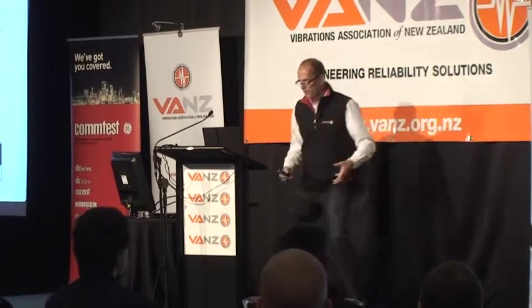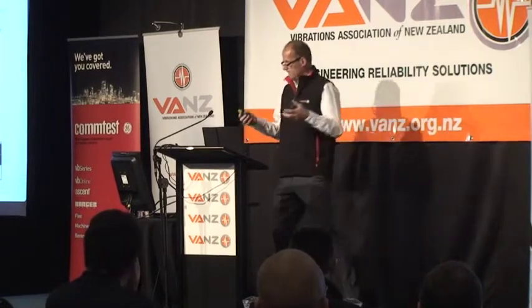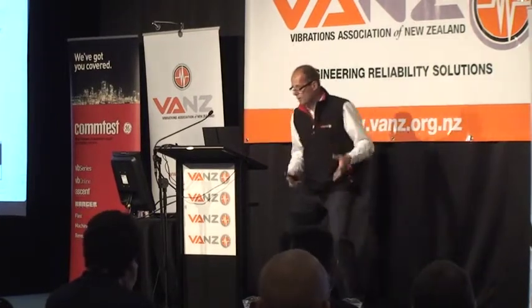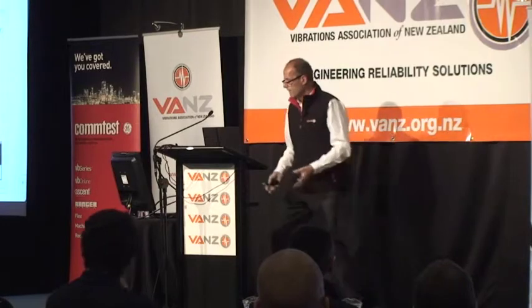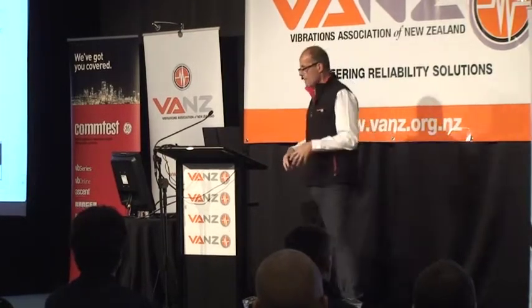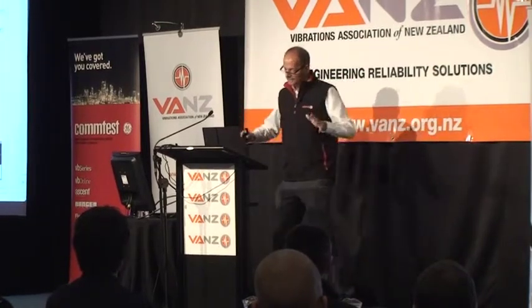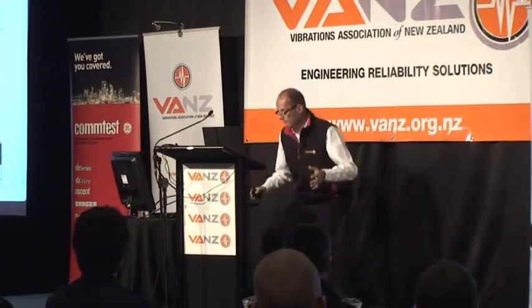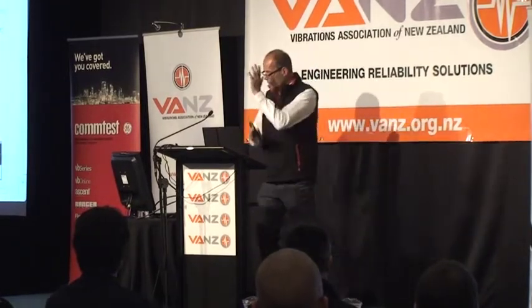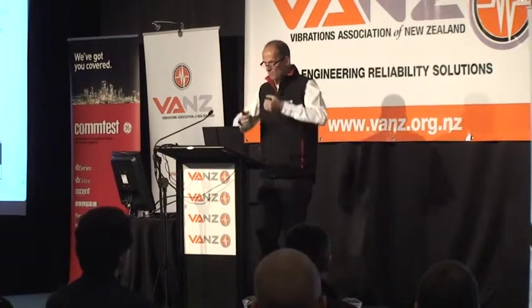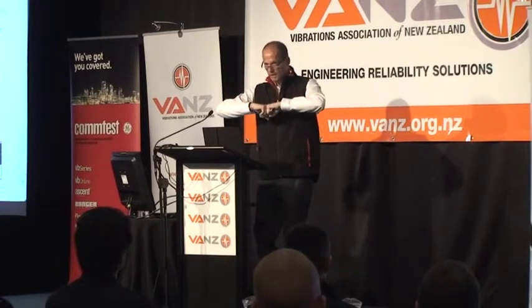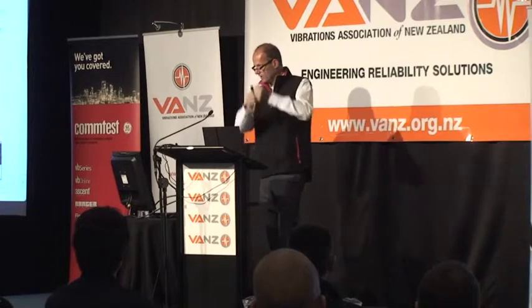So before, I have this motion, like unbalance. Well, knowing that it's this sort of motion tells me something. Now, you might think, oh, don't all machines sort of rotate like that? Well, in truth, if I was misaligned, I would move in more of a tight, maybe even a figure eight, but it's more in one plane than another. Because of the way the machine's been aligned, it's hard for the machine to move in that circular motion.